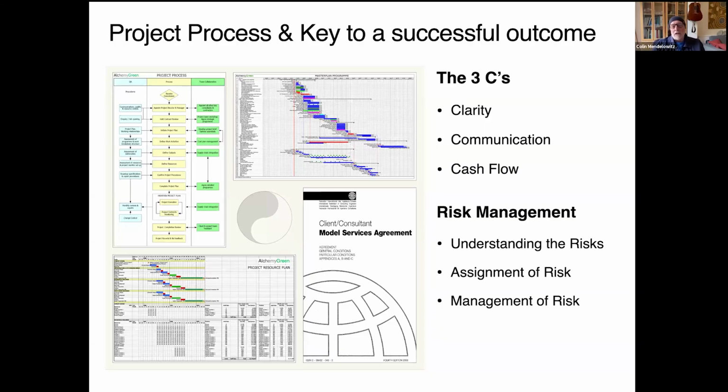Traditionally, the route would be for an architect like me to do a design, get planning permission, produce tender documentation, get 3 or 4 contractors to bid, and then sign a contract. The problem with that is that when you choose a main contractor, you are assigning the risk to him, and he will price that risk.